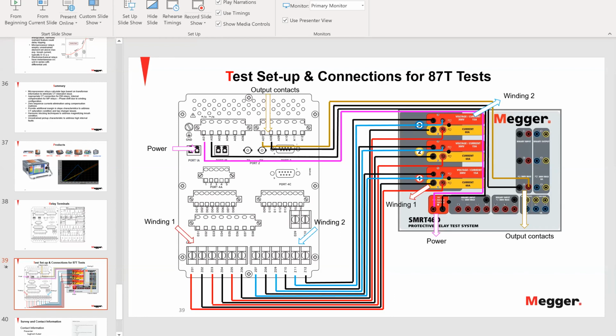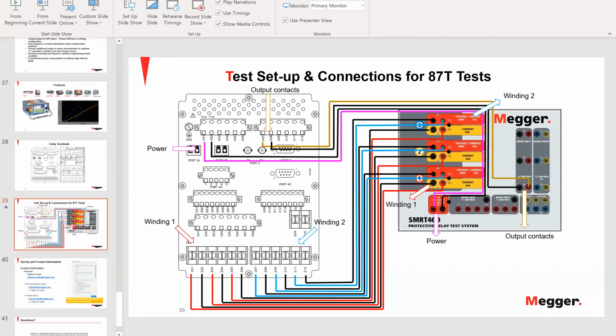The 745 relay in general uses Modbus for communication. So we do have a feature of reading Modbus settings. So the answer is yes, we can read that. All you need to do is find the Modbus address, the slave address for the element. If everybody is familiar with the Modbus communication protocol, all we need to do is first map it in the software. People can get in touch with me if they require training in understanding how we are reading Modbus, or any one of us, and we will be more than happy to help you out on that.